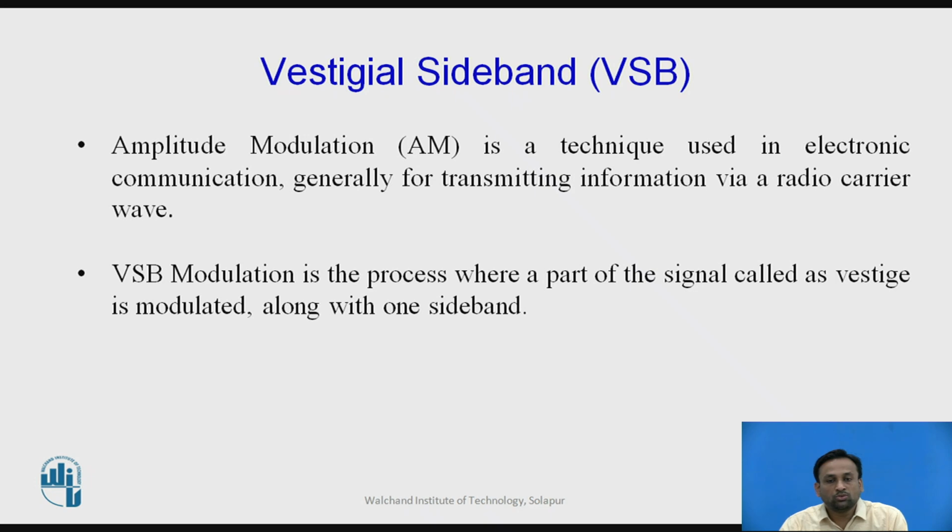That's why we go for a DSB-SC signal, in which we suppress the carrier and send the two sidebands. But the two sidebands carry the same information. So for particular applications where the power is reduced to half, only one sideband is sent, which is known as SSB.